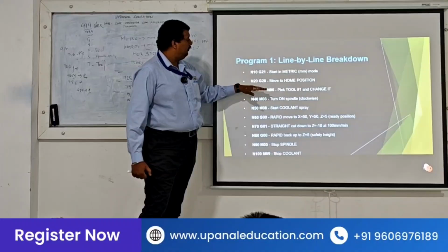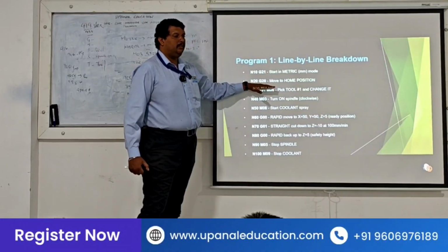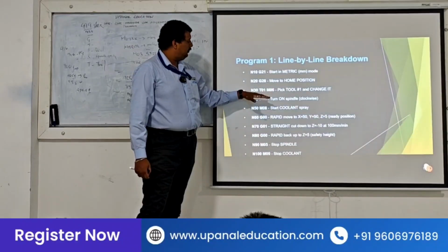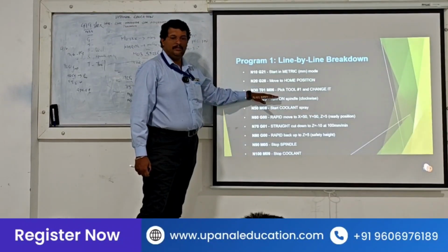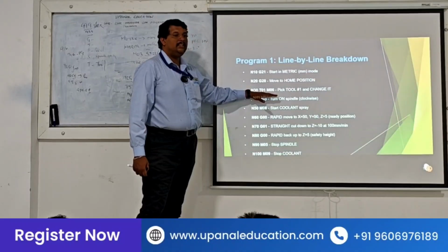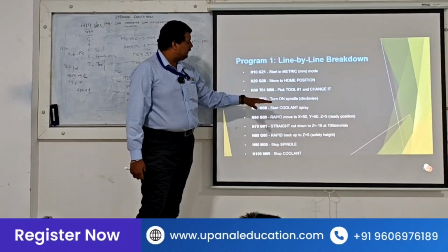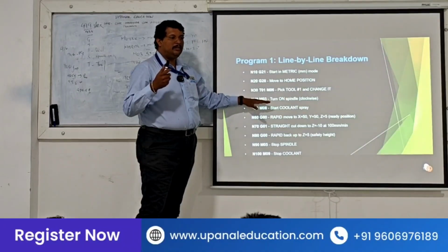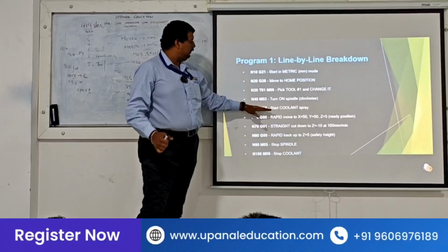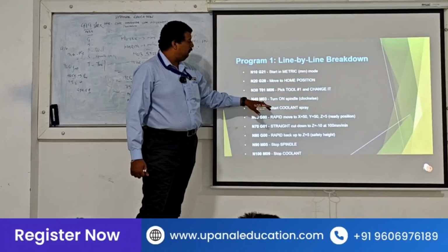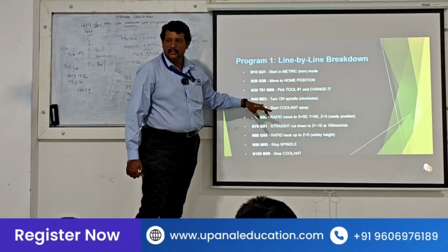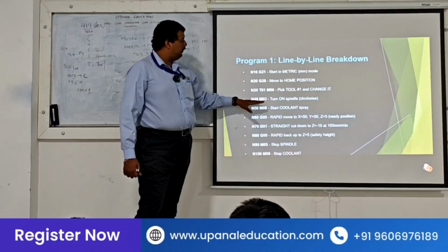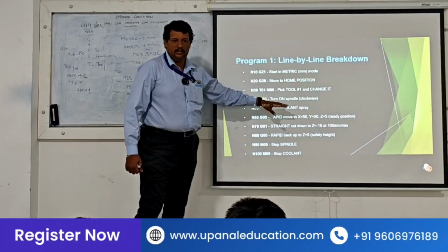Then next line we tell it to go to G28, the machine home position. Why? Because I want to change the tool. Next line is T01 M06. Once the tool is changed, what should I do? I have to turn on the spindle. So spindle on will be the next thing: M03. But here there is a small mistake, I typed wrong. I have to put the spindle speed also. We will put M03 S8000.